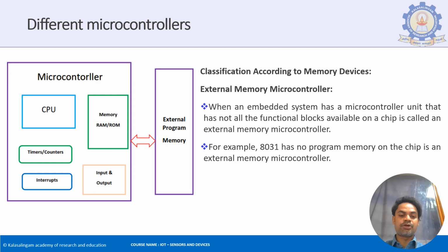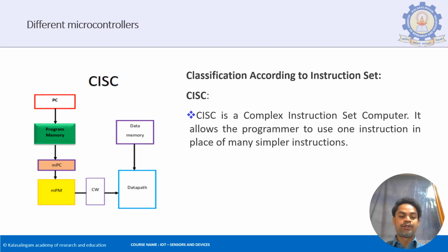The opposite of that is going to be the external memory, in which the program is going to be stored externally, whereas all the data, everything else is stored internally over here. You have another external memory which is available, which is connected through this external interfacing bus. So this is an example of what external memory is. For the embedded memory, the example was 8051, whereas for your external memory, the example is your 8031 microcontroller.